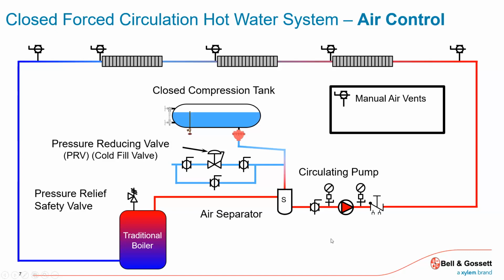The boiler shut off, the system cooled down, possibly some of that air got absorbed by the system water, and then we just kind of had this movement in and out of solution. We didn't want to get rid of it because if we added automatic vents, these are manual vents, but if you had an automatic vent and the vent vented, doing its job, you'd be lowering the system pressure. The reducing valve would see, hey, there's a drop in pressure on my diaphragm. I'm going to add some more makeup water. Well, the only place the makeup water would go would be into this tank. And all of a sudden you're starting to lose that spring.